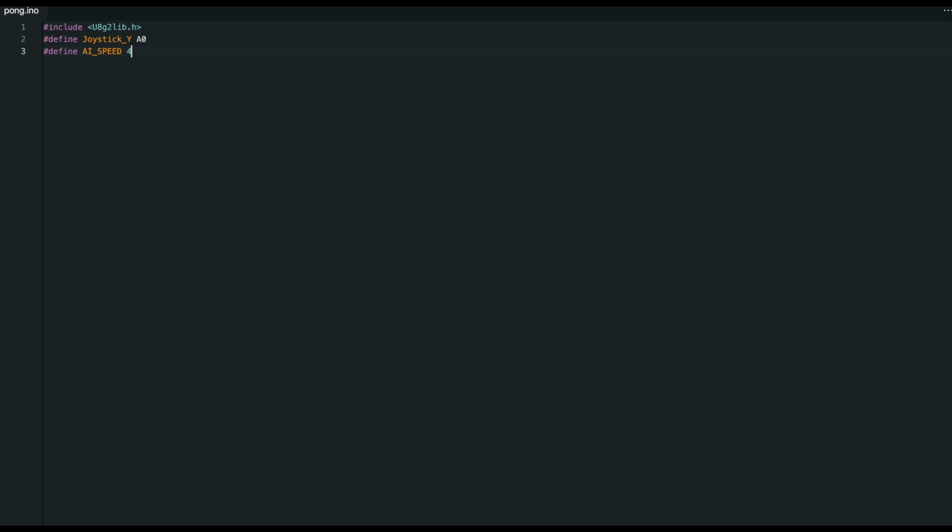Okay. So down here on line 5, I'm going to put some white space between my preprocessors and my constructor. The constructor is going to be used to create the object that we will use for U8G2 for the OLED. So the constructor goes as U8G2 underscore. Oh, my bad. It's in all caps. U8G2 underscore